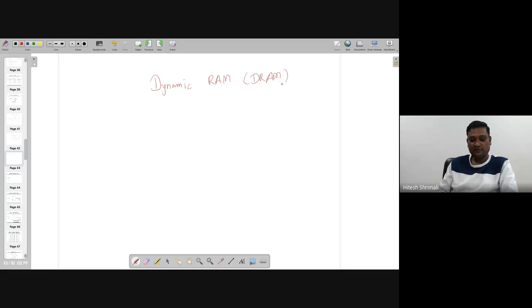Notably, the memory organization at the top level will be the same as what we did for SRAM, where there is a row decoder and a column decoder, and in between there are cells where you use a word line and bit and bit bar lines, so that you can read, write, and hold the value which you want.